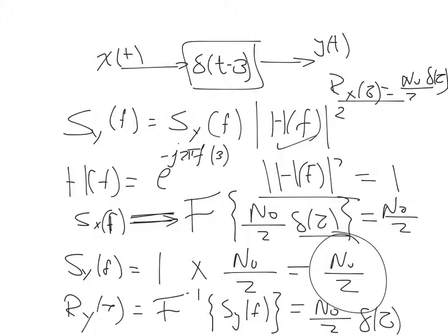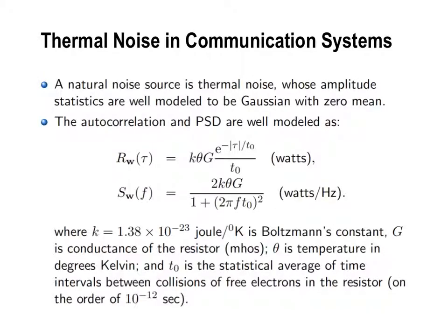We can only do this if it is stationary, right? Of course. If it's not stationary, you cannot do the whole thing. We cannot even put this relation. Right? Because this relation is true only for the case of stationary, right? Because the only thing that has a power spectral density is a wide sense stationary random process. Okay? Another example? We will do some other examples.